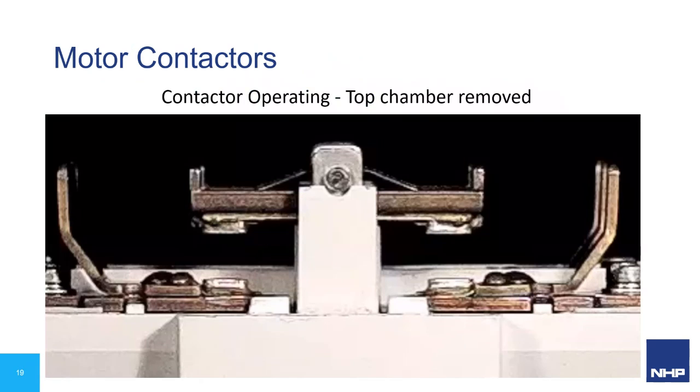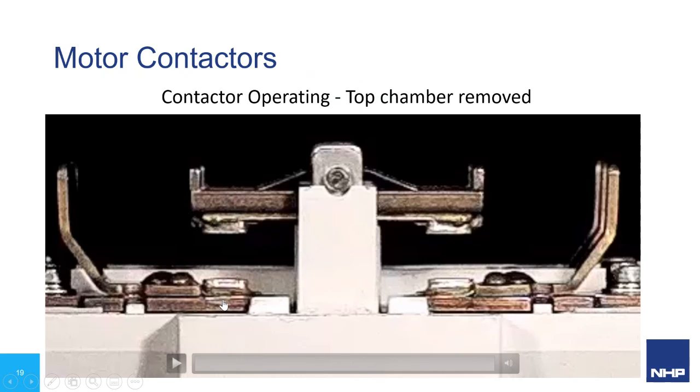So let's look at the behavior of a motor contactor in this application, because we've got a circuit protector being the main circuit breaker, and we'll have a contactor which starts and stops this operation. Contactors are sized and rated for duty according to AS/NZS 60947 Part 4.